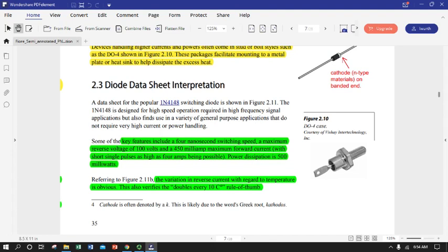We went over the difference between forward bias, in which an external voltage was helping push charge carriers up or down the hill, and reverse bias, where the charge carriers in the diode were being pulled away from the interface, and therefore the energy hill was effectively being heightened and steepened, and so no current would flow. So we concluded the diodes act like one-way valves for current.